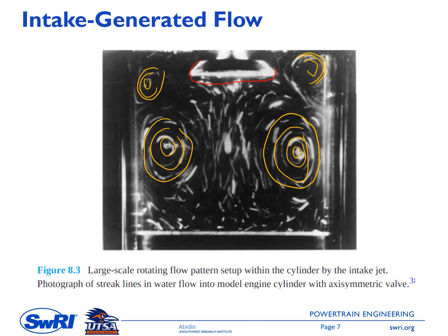If we can have a faster burn rate, then we'll have better combustion performance. But as you might know, in a spark ignition engine, the burn rate might be limited by the peak cylinder pressure and thus knocking. In a diesel engine, it will be limited by the peak cylinder pressure and thus the material of the cylinder head, liner, piston, and so on.